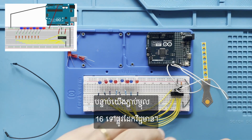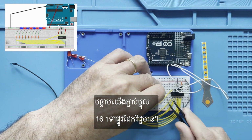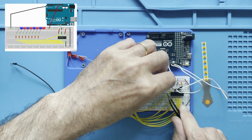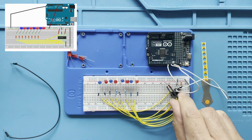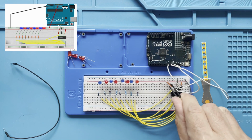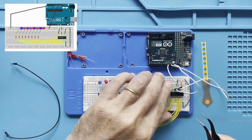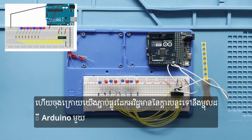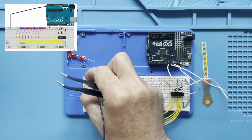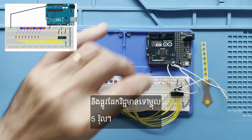Next, we connect pin 16 to the positive rail. And lastly, we connect the negative rail of the breadboard to one of the Arduino ground pins and the positive rail to the 5-volt pin.